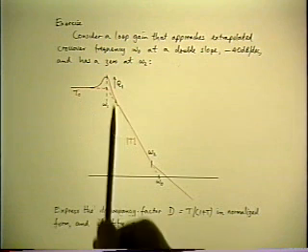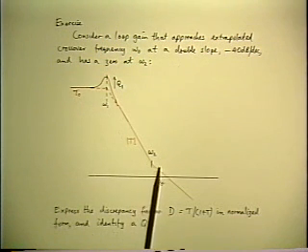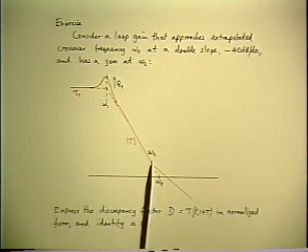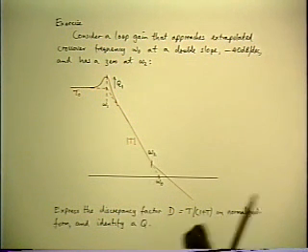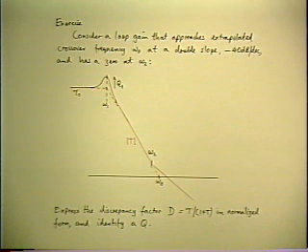And since the stability of the entire system depends on the position of this zero, the worst thing to do is to make the zero dependent on something like an ESR, which is a poorly controlled parameter and is parasitic anyway.